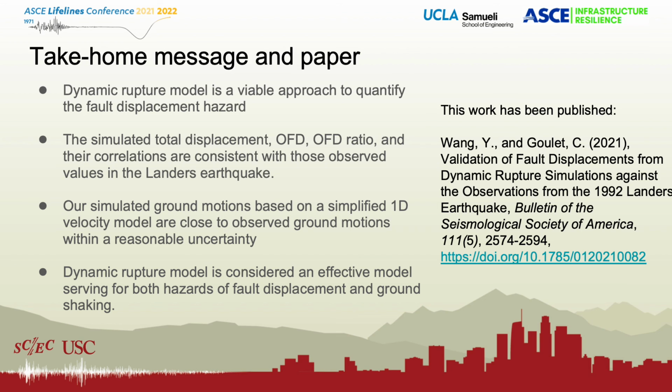And our model can also simulate ground motions that are comparable to observed level of ground motion within a reasonable uncertainty. So in summary, dynamic rupture model is considered as an effective model to serve both hazard analysis of fault displacement and ground shaking.